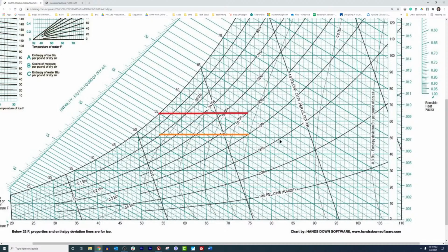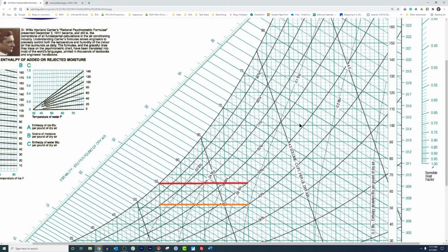Understanding that heating does decrease relative humidity, but it does not decrease the moisture amount in the air. Understanding that chemical removal of humidity can be done without affecting dry bulb in the form of desiccant, and that we can add humidity to the airstream, potentially not affecting dry bulb depending on our humidification. If you understand this one chart, it will help you substantially.